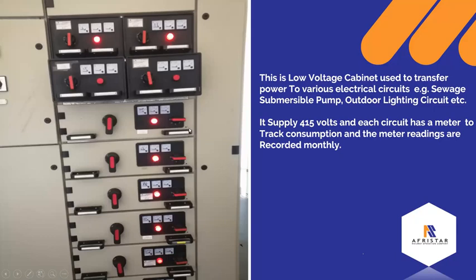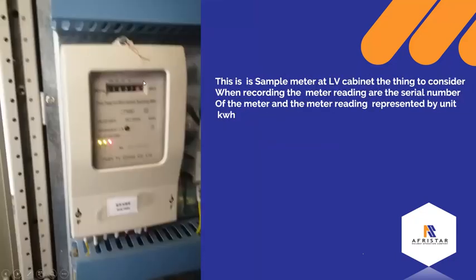Each cabinet has 415 volts, and a circuit breaker calibrated according to its load. Also, each cabinet has its own meter to understand the power consumption of each equipment. These readings are usually collected monthly on how various buildings and equipment have used power.